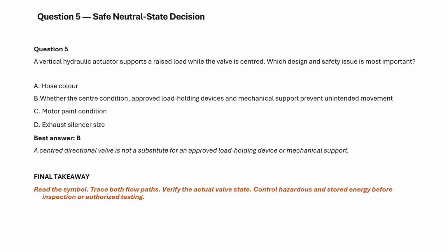Final takeaway. Read the symbols. Track the flow path. Verify the actuator and valve state. Control hazardous and stored energy before inspections or authorized testing.